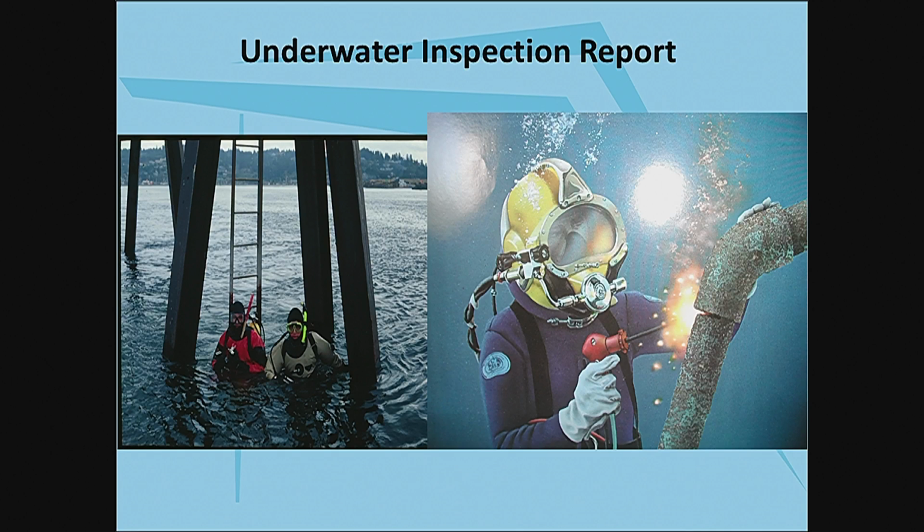The next report is the underwater inspection report. And we have a dive team, ODOT dive team of 2 permanent divers, and we have 6 part-time divers. And these are done on a frequency of anywhere from 12 months to 60 months. And they, as I said before, they dive on our 7,400 bridges. When I say ours, that's yours and the state's. We have a total of 7,400 bridges that are 20 feet or greater in length. And when I say 7,400 bridges, they're not all over water. So I probably need to backtrack on that a little bit. But I think each year they probably inspect 750 bridges underwater, our ODOT dive team.